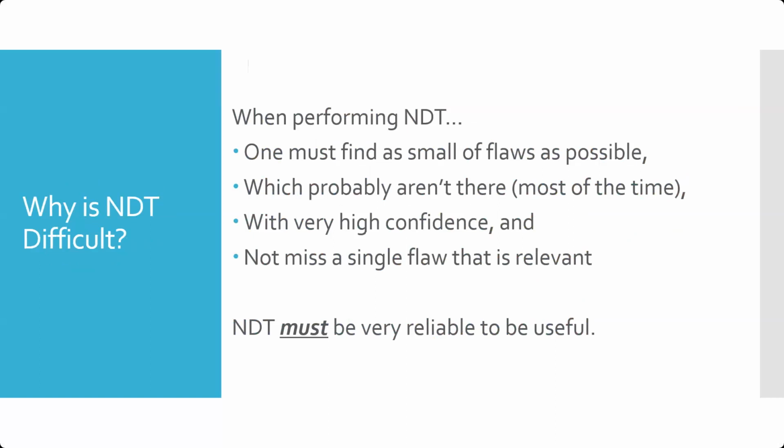However, those small flaws probably aren't there most of the time, by far the majority of the time. We have to have a very high confidence that we will find the flaws when they are present, and also that we don't create extra work by misidentifying or having false positive results. The high confidence is that when there's a flaw, it'll be found, and when there's no flaw, you won't say there's a flaw. And finally, not miss a single flaw that is relevant or over that threshold of criticality. And so NDT must be very reliable to be useful.